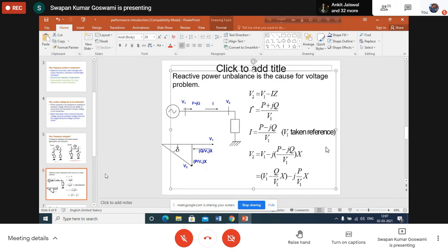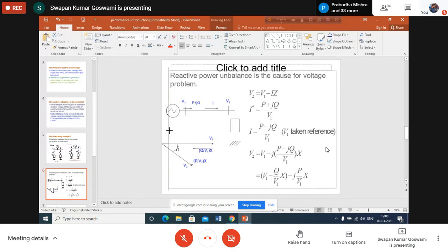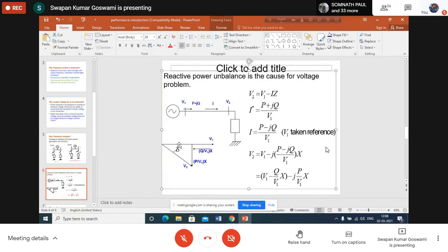That's why we can say that in a high voltage system, obviously this is true for a high voltage system. This will not be true for a distribution level voltage, distribution system. But basically, any change in the voltage, any control of voltage will be mostly at the higher voltage part of the system, not at the lower voltage part. When we want to control the voltage, all these things will be mostly done from the high voltage part of the system. At the lowest level, there is very little scope of doing this. That's why we are assuming that our system is at high voltage, because any control regarding the voltage variation we shall be doing by doing something at the high voltage part of the system.